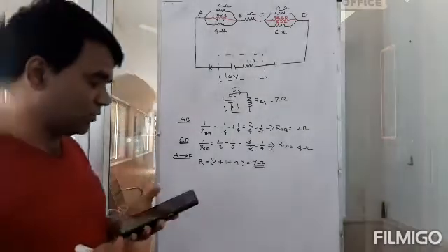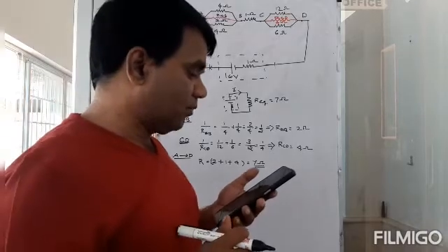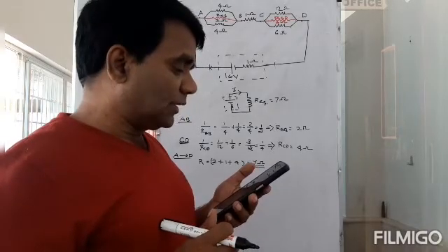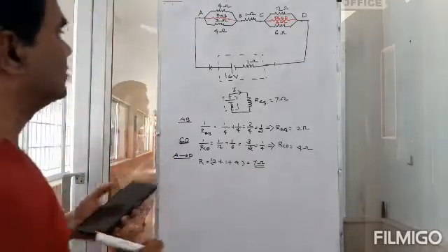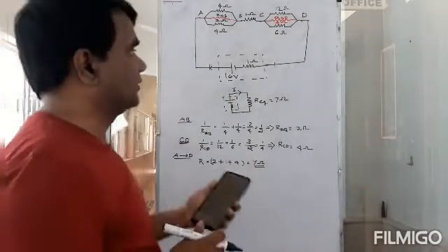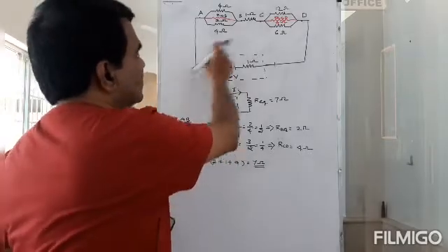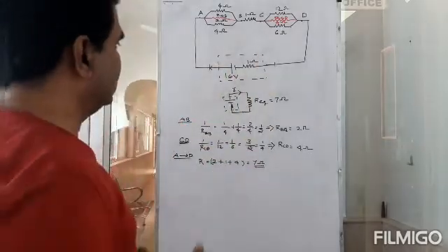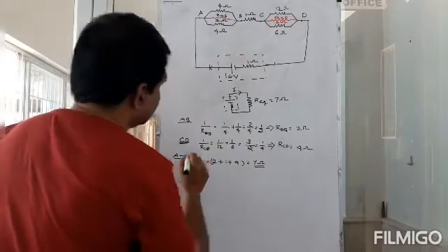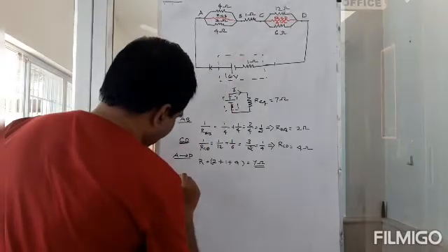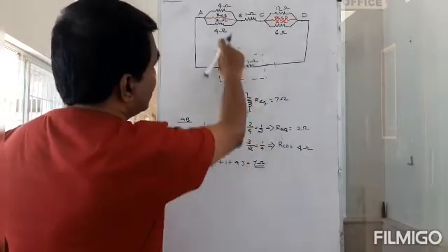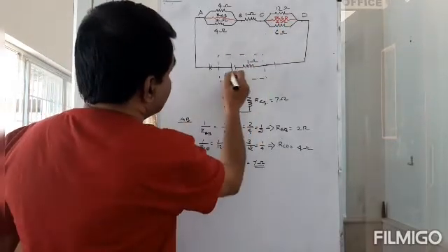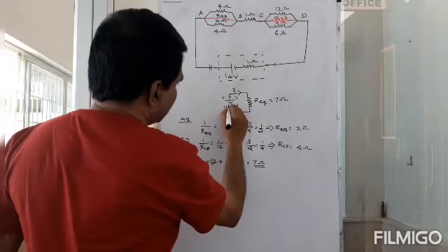What is the second part of the problem? The second part is: obtain the current in each resistor. First, let's take the total current from the battery. That's easy. What is I? The 7 ohms is the effective resistance, and I have 1 ohm here, internal.